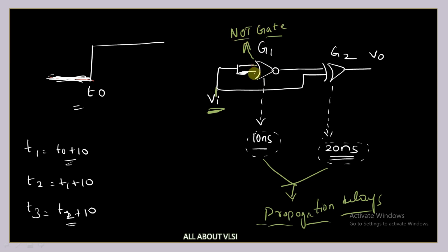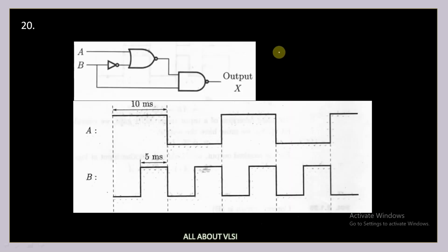In the logic conversions also we have seen, right? If you are shorting 2 pins of your NOR gate, or 2 pins of your NAND gate, it is going to work as a NOT gate. So this is simply a NOT gate. Now this is an XOR gate. First, here we need a complementary output.